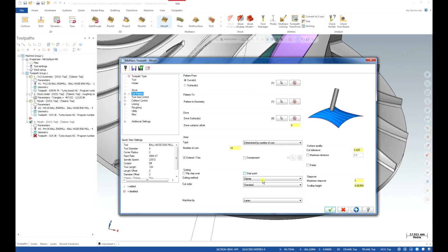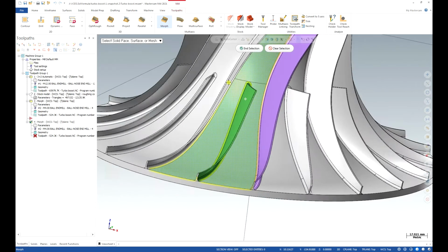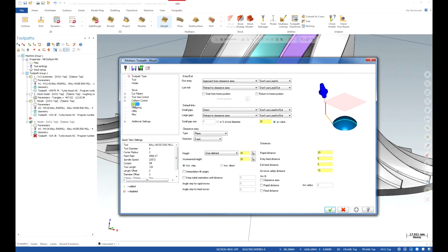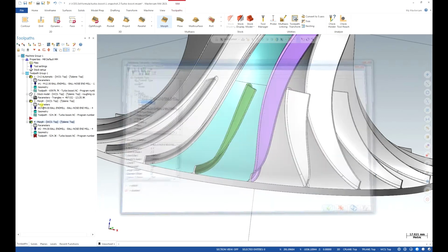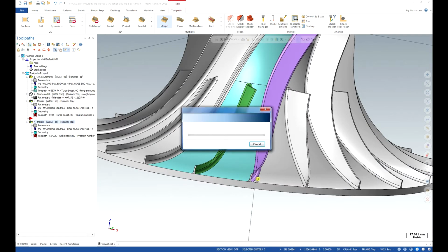Nice. And the dry surface, we are going to select the floor, of course 0.3 stock as on the top part. That's good. And extend trim, we're going to extend start and end 2 mil as we are going outside the edge. Hit the regen button